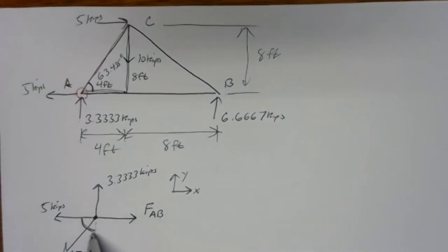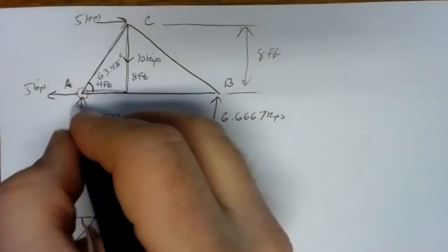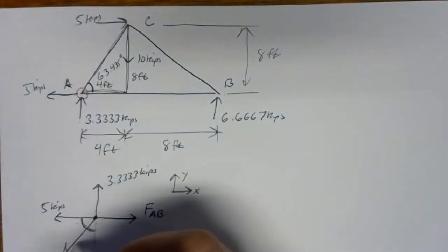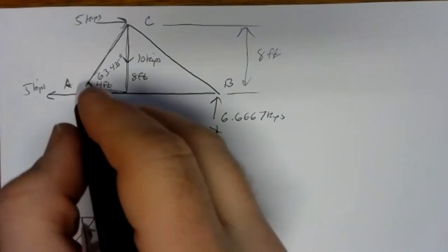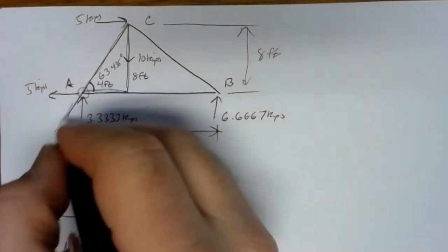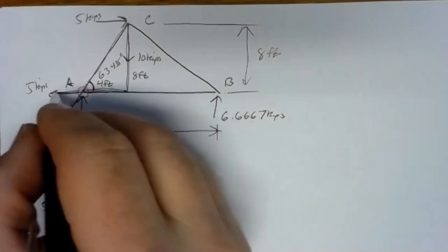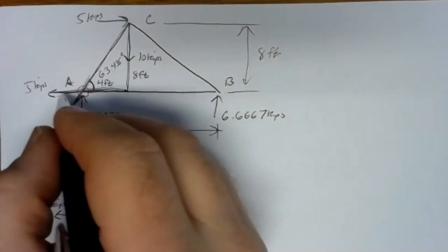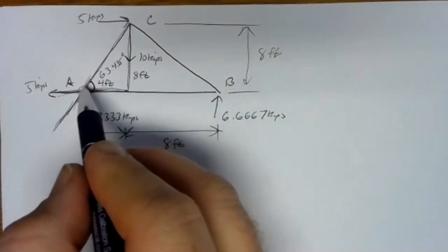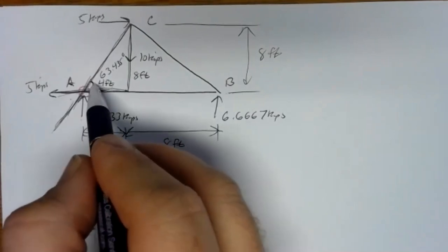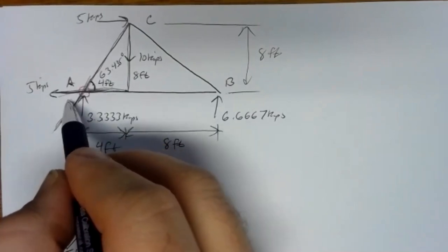Now, be careful translating that down here into the free body diagram. Very common error, somebody puts it in the wrong place. Be sure about it. Draw what you've got down here for your force and your arrow up here. If you draw kind of a cross here, or an X, angles that are opposite each other are the same.